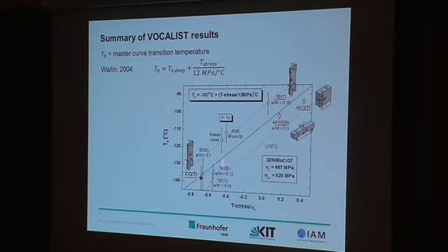And you have, of course, some scatter, but you see a clear trend, and you can parameterize the fracture toughness using the single parameter, the crack tip T-stress, and for instance assess such a low constraint geometry like CCT specimen, or also called MT specimen, using the fracture test data obtained on CT specimens.